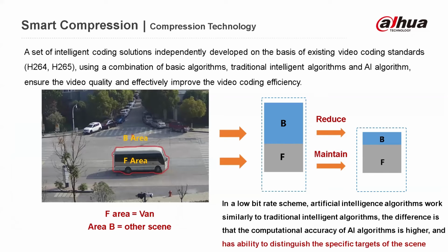Then when we look at compression logic, if we have a camera monitoring this area, compression is achieved when we maintain the main background frame or the background image because it's not going to change, and only record the changing aspects. Like if this bus is moving from area A to area B, then we only record that bus and overlay it over the same scene. That helps us because instead of having 50 images with the same thing, we just keep one image and record the small details using the compression. So with this, we save on space.